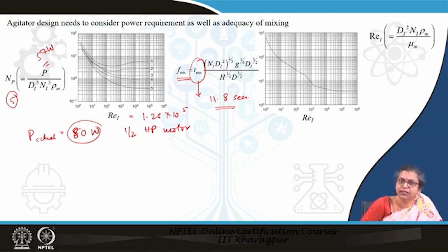Now, if you want to go for a larger scale, quite naturally you will have a larger volume. According to the volume, the diameter of the vessel has to be designed. Once the diameter is designed, the height, the impeller, and the power required can be designed accordingly. So, this was just the simplest type of extractor, a single stage contact. We have adopted a single stage contacting device because in this particular case the selectivity of water was very high. So, therefore, single stage was sufficient.